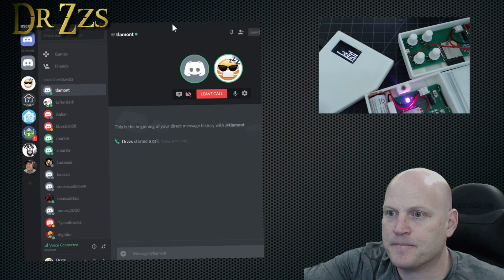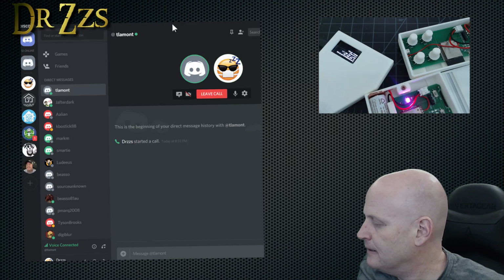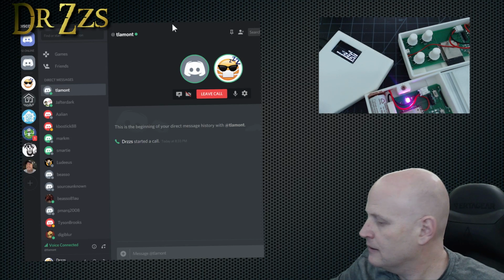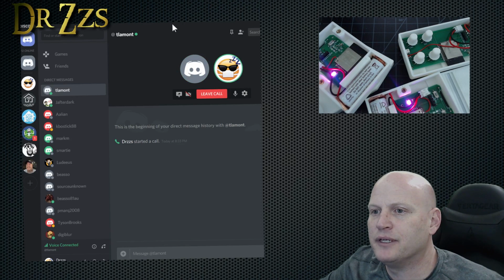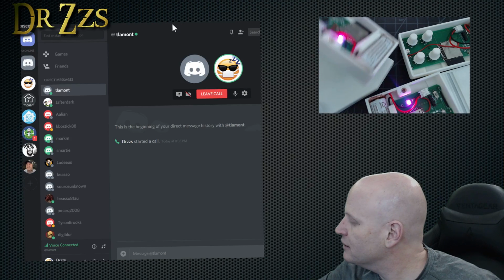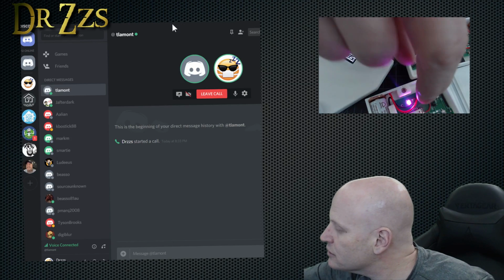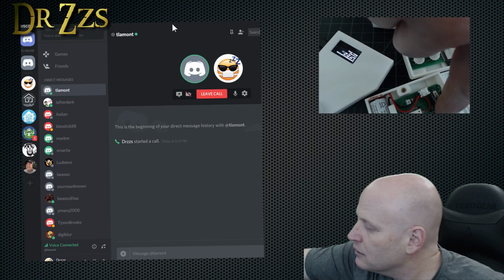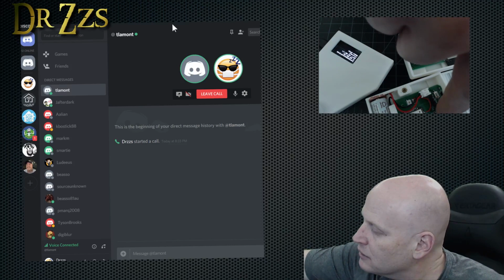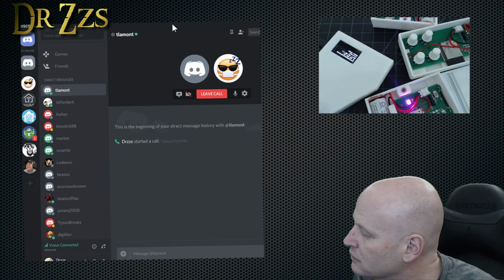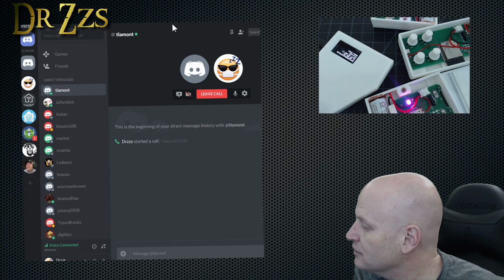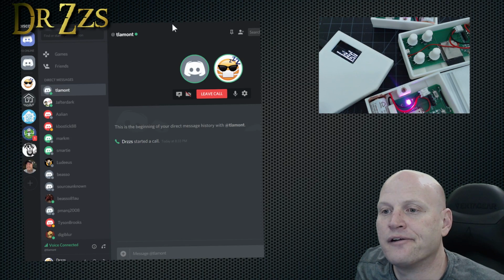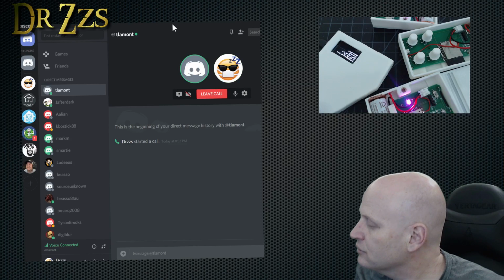It will be the device. Did you want to try the other door sensor and see if it pairs? I did. I've got them both here, and neither one of them has done anything. I can try the reset button again. I may need to send you an updated bin file for that. Hoping that light will go off, and it just stays on. If that light doesn't go out within about 3 seconds, it won't.